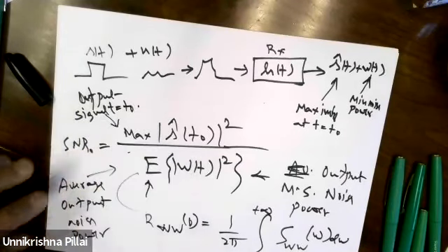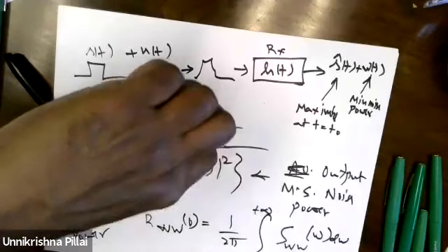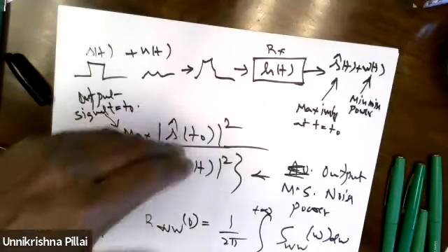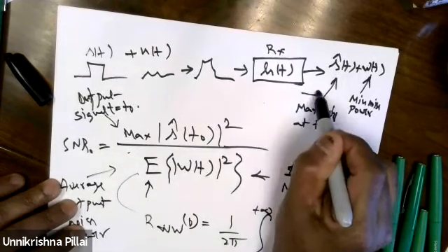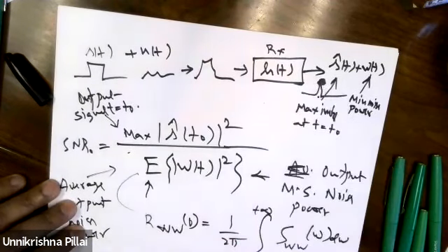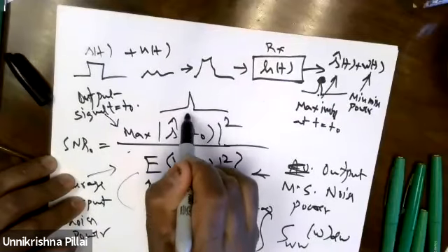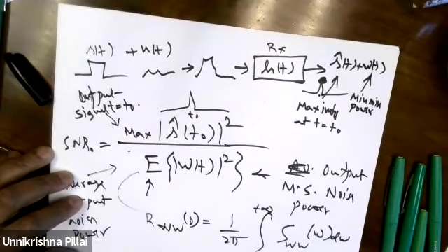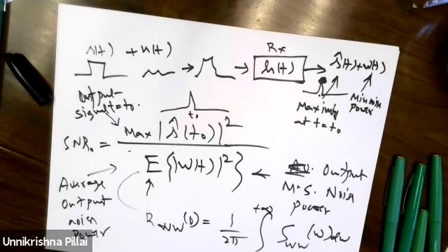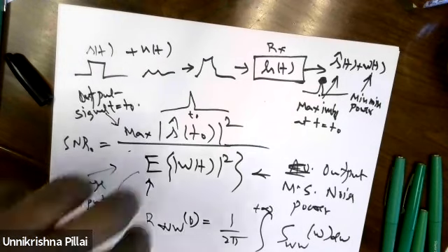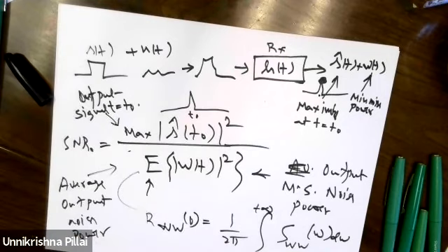So the whole idea, you see, is very cleverly done. Here we are not taking anything average, because we are hoping that the filter did its job and compressed the pulse, so the output is a pulse. And the pulse is peaking at t equal to t0. Because of this very constraint, the filter will be forced to compress. That's the hope. This is how you train the filter what to do. You put your desire into the objective function. Our actual desire is to compress the pulse, but how do you express it?